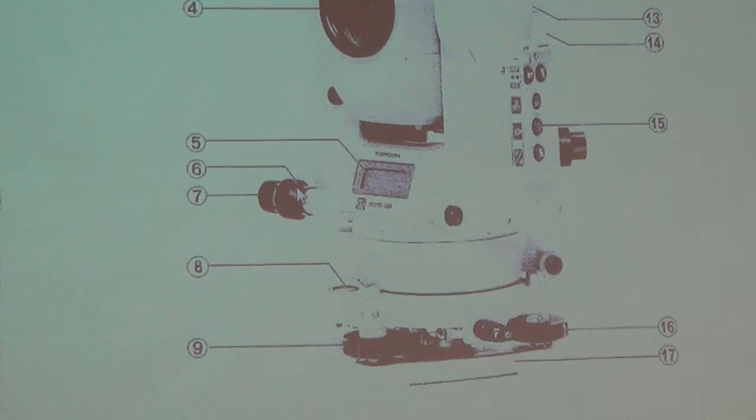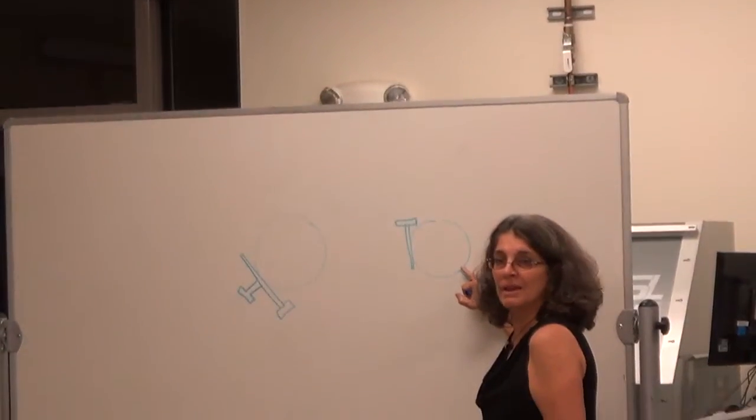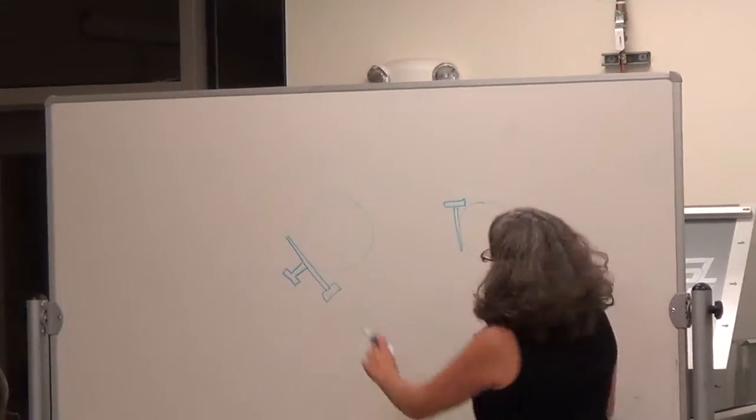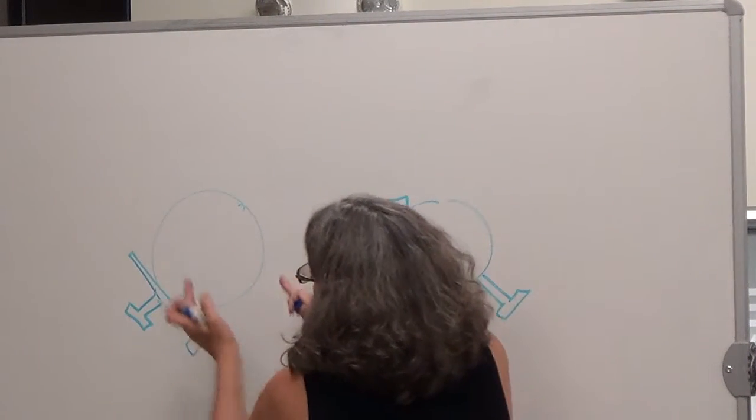on the theodolite, this is a top view, you would have a tangent screw, and then there would be one screw coming out. And then you noticed on the upper one, in the upper plate, there was just a screw like this that was locking, and then you saw somewhere else this screw, right? Remember that? So which one locks? The perpendicular one, because it's a screw, and you shove the screw there and it locks it, right? Okay. This one's allowing it to turn a little, this one, it's a tangent screw.